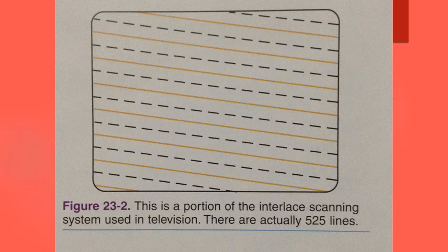Scanning. Scanning is the point-to-point examination of a picture. In the camera, the electron beam scans the electron image. It responds to the point-to-point brilliance of the picture. The scanning system in the United States is the interlaced system. It consists of 525 scanning lines.